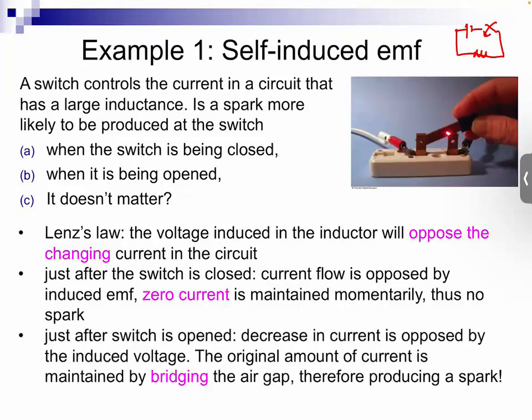But then if your circuit is already closed to begin with and current is already flowing, when you open the switch, then Lenz's law says, I would like to maintain some current flow in the circuit. And so induced current will be produced to sort of bridge the gap, so that the current does not immediately go to zero, but it will go to zero slowly.